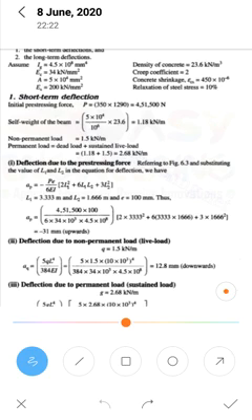Next, the non-permanent load is given in the question, that is 1.5 kilonewton per meter. That is given in the question, so you can take it directly. After that, there is the permanent load of the dead load as well as the sustained live load, so you add these two. Finally, the permanent load will be 2.6 kilonewton per meter.